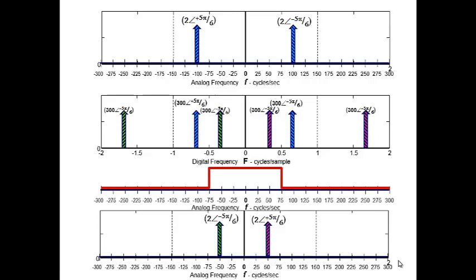Okay, but everybody's all right with this? So that cutoff frequency comes from the sampling rate? Once we define the sampling rate, that defines what cutoff frequency we need for the recovery process. Okay. So we went from those top impulses to the bottom impulses. We didn't change the magnitude, but things moved in frequency and things shifted in phase. That's kind of weird.